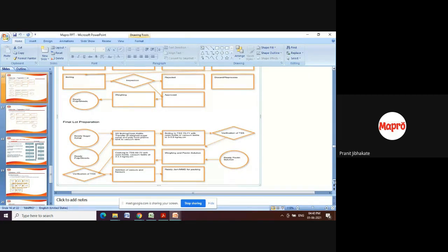Okay, here you can see that ready sugar syrup, ready pulp. After adding, we can boil it in an open kettle or vacuum pan also. So at what point are we boiling it? We are boiling it up to 70 to 71 degree Brix. Okay, and in the vacuum kettle, the pressure is maintained at 3.5 kg per square centimeter.